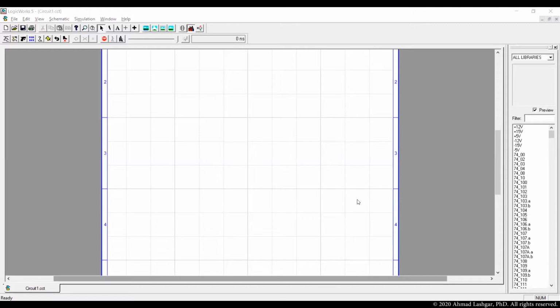In this video, we are going to make a decoder. Decoder is a circuit to translate an input code and activate the corresponding line on output. Decoder has n input and 2 power n output lines. All output lines are 0 except the line coded in the input.